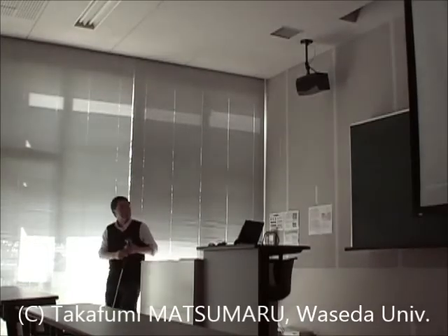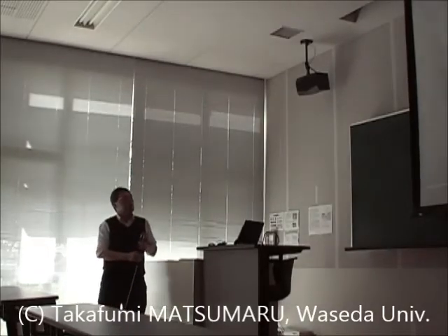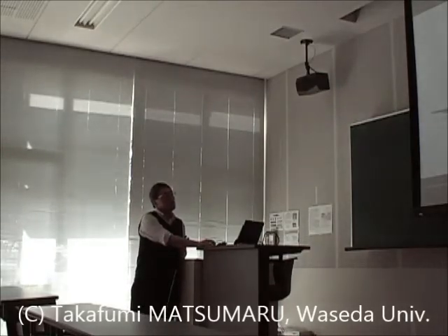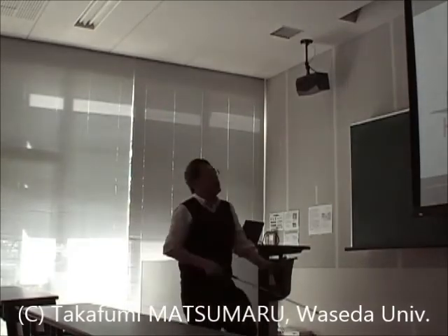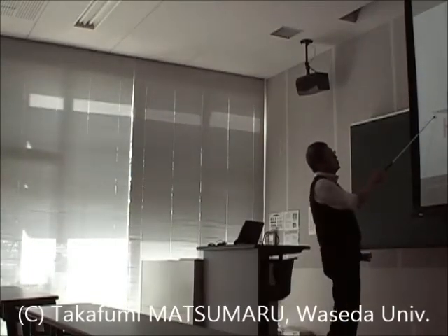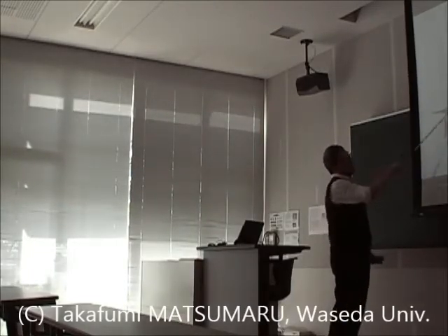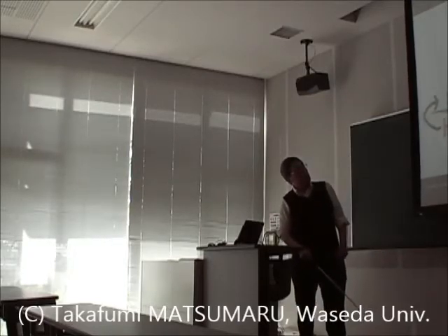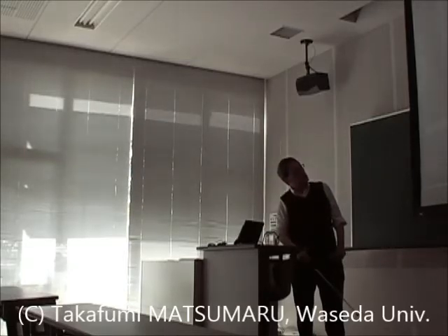But how do these vortex generators work? When air is being redirected around an object like a piece of plywood or maybe an airplane wing, and lift is being generated, there is a lower pressure on top and a higher pressure on bottom. And this higher pressure can escape to the low pressure around the wingtip. This causes all the high pressure air to move outward and all the low pressure air to move inward. These sheets of air are called vortex sheets, and at the tip they roll up into a vortex.